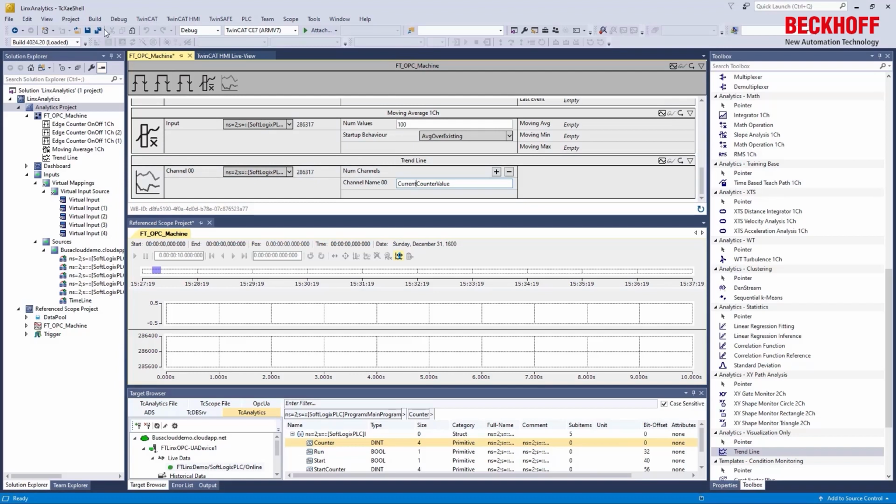Okay, now that I've modified this project in the workbench, you hit save, and really we just run through that same deployment process again. TwinCAT Analytics deployment will update the TwinCAT project in the background that we saw was generated, and it'll update our dashboard, and we'll have all these modifications shown immediately on the dashboard without any programming, just one-click dashboard, one-click generation of this analytics runtime. That's great. All right. So now let's take a look at some of these things together.